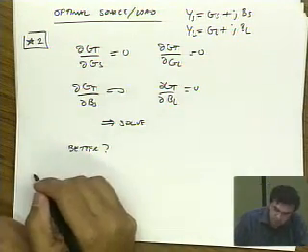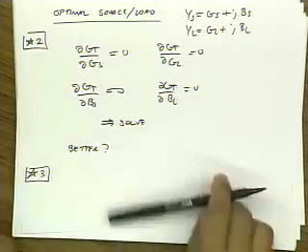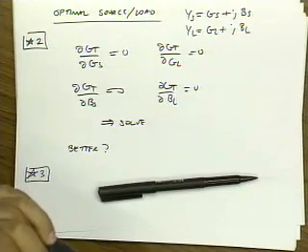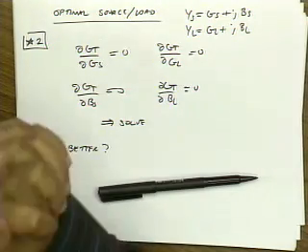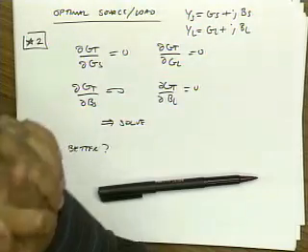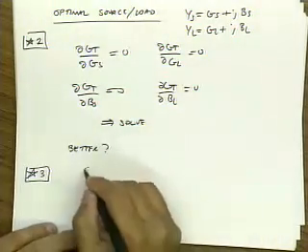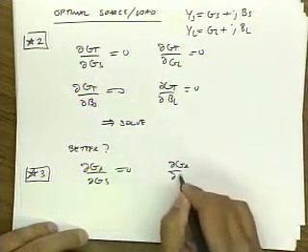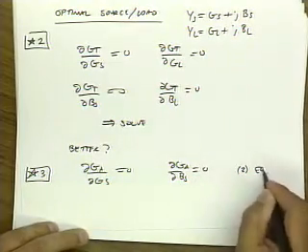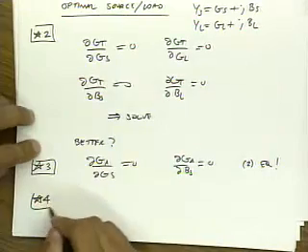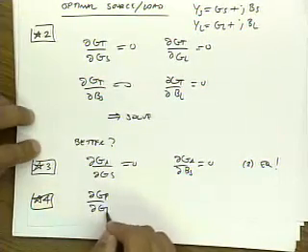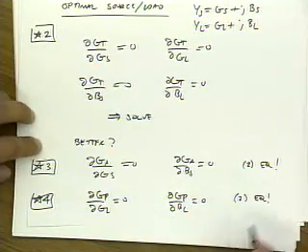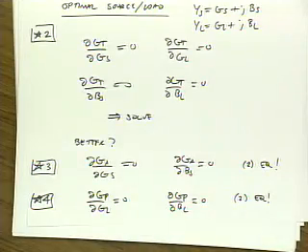Okay, well, a third approach is to realize that when GT is maximized, it's actually equal to GA, and it's also equal to GP. And GA and GP are only a function of one admittance. So in effect, they're only a function of two variables. So I could take the derivative of GA with respect to the source. That's two equations. Or I can also equivalently take it with respect to GP. And that's also two equations. So that's actually the better route to take, because you only have to solve two equations.